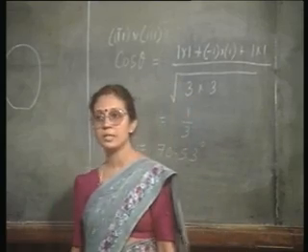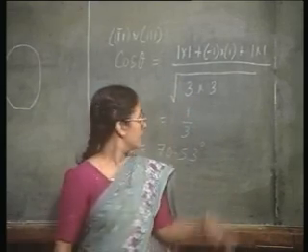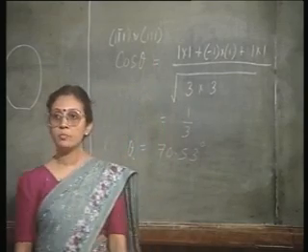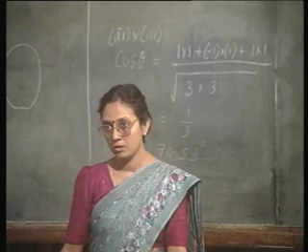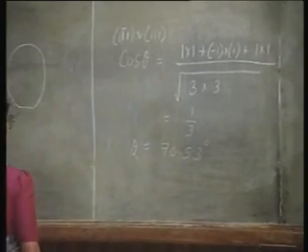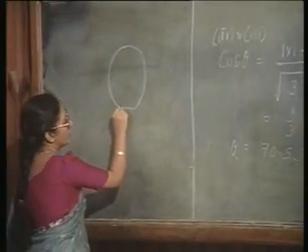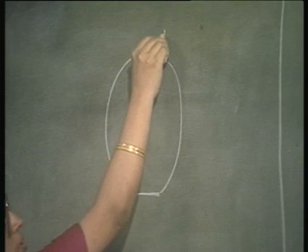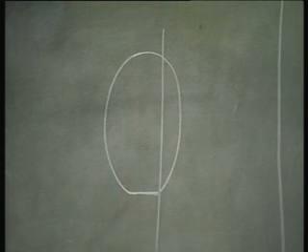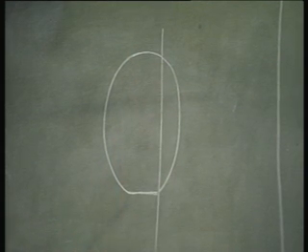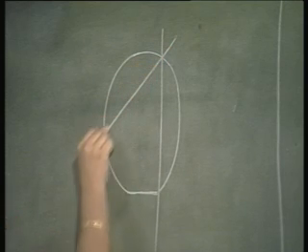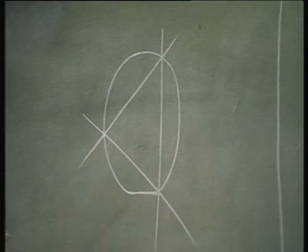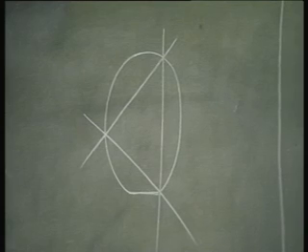But the important point is, even these two planes, they are going to meet in 110 direction. And where are these 110 directions? See, I have provided a flat. Therefore, my first scribe line is going to be perpendicular to this flat. Okay. So, this is 110 direction. Where are the other two 110 directions? You know, right? It is going to be like this.